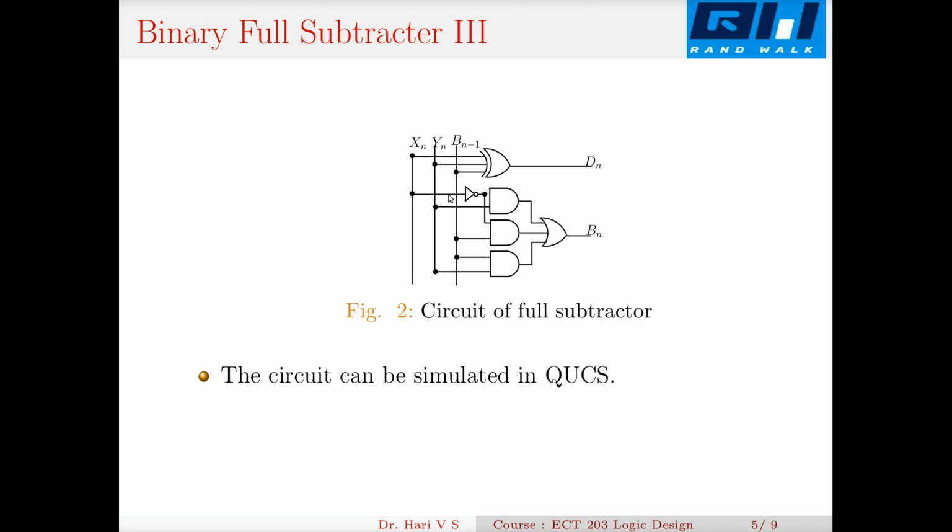Then I need an inverter. Either you can put in a new chip like a 7404, or you can make one, because you are using 3 of these exclusive OR gates in this circuit. You have one spare gate there, so you can convert it to an inverter. How do you convert an exclusive OR gate into an inverter? You tie one of the inputs to logic high, and apply the signal to the other input.